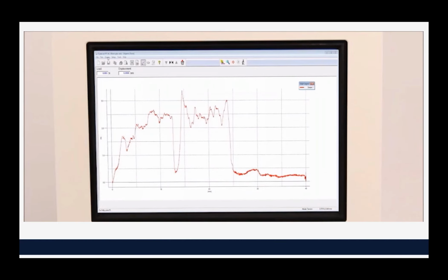And these are the typical graphs. And again, depending on how evenly the adherent or the adhesive material is coated on the test sample, you'll either see a clean linear graph or what you're sort of looking at here, which essentially is the reason why you test. This graph seems to indicate the applicator is not applying a uniform amount of glue or adhesive on this particular test sample, or the substrate wasn't properly prepared.